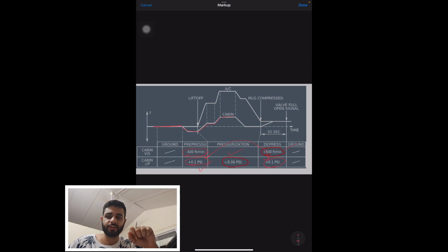In case I'm doing a go around, then it will maintain that 0.1 throughout. In case when I'm taking off also, it will give me 0.1, so that at sudden rotation, they don't get that jolt of sudden pressurization. It's passenger comfort. If they didn't want to keep it, they could have left it, and the aircraft would operate fine. It's just passenger comfort, and passengers are paying money.